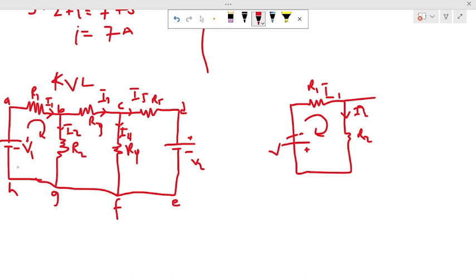the voltage drops across all the resistors here. And with Kirchhoff laws, we have to traverse in a particular path, and that path is going to determine our sign convention to use. So when, for example, we traverse in the path A, B, G, H, A, in order to know the sign of the voltage that we are supposed to use, this really confuses people, but this is what you are supposed to do. In order to know the sign that you are going to need for V1, this is what we do.